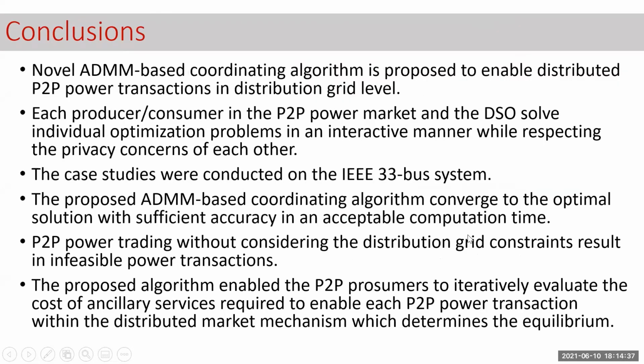Going into the conclusion, this ADMM-based coordination algorithm enables P2P market clearing under the consideration of ancillary services. Also, we still respect privacy concerns, because ancillary services are always computed centrally. So you need to take some information, but here we have only shared the power exchanges, which are not that private. The prosumers will anyway be sharing those power exchanges with other prosumers in the system.